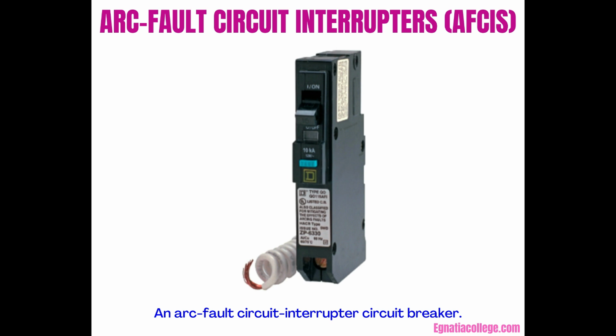This figure is an arc fault circuit interrupter circuit breaker that would be installed in the main panel branch circuit side. The current from a series arc follows the normal circuit path. Parallel arcing occurs between two conductors. The arcing may occur from line to neutral, or line to ground. Parallel arcing current does not follow the normal circuit path.